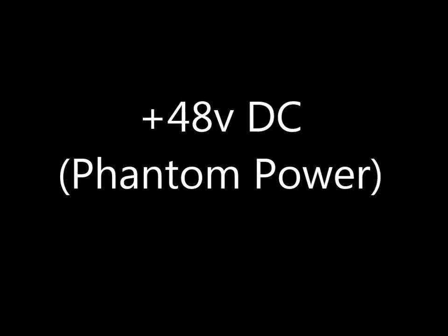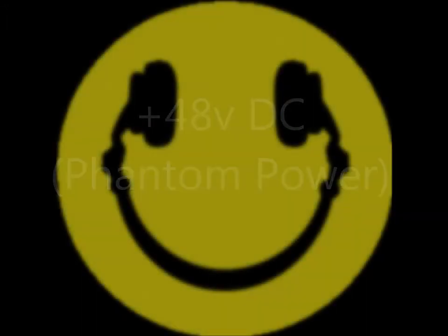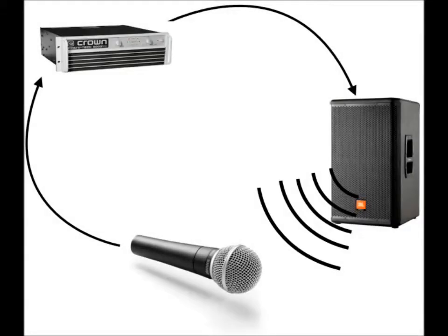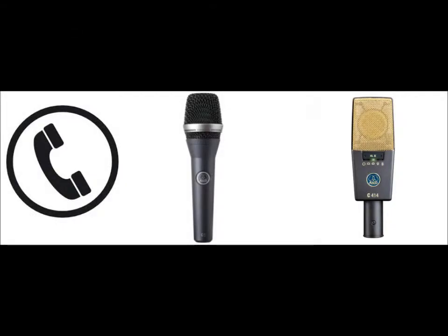Condenser mics are more sensitive and can provide a smoother, more natural sound, particularly at higher frequencies. Be wary of using them on stage because they are susceptible to feedback. Should you do so, position them carefully with respect to the stage monitors. Condenser microphones are used in everything from telephone transmitters to inexpensive vocal microphones to studio recording microphones.